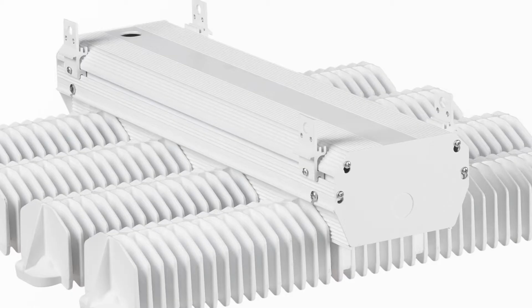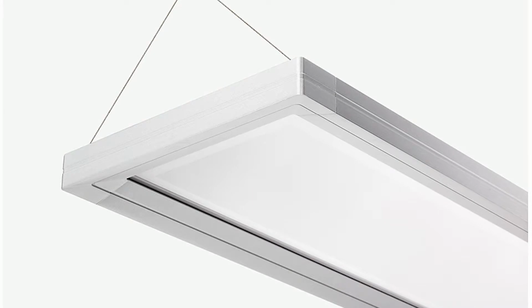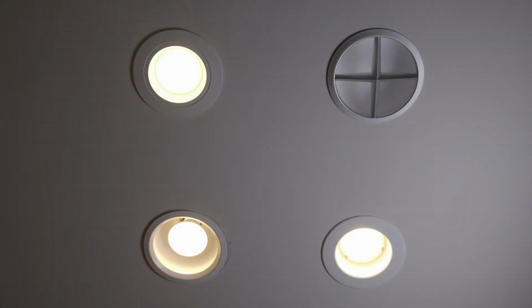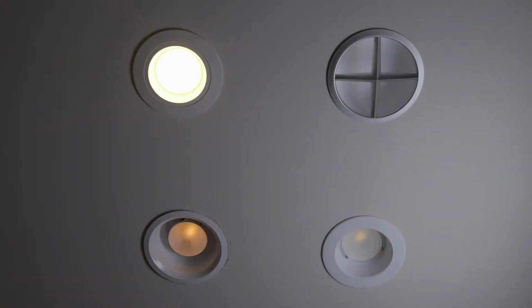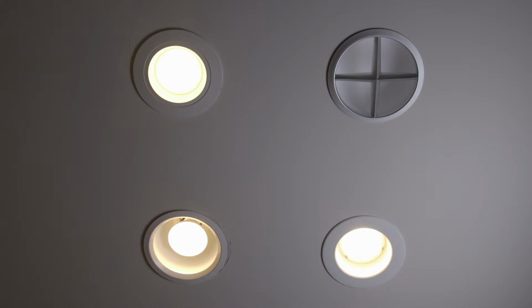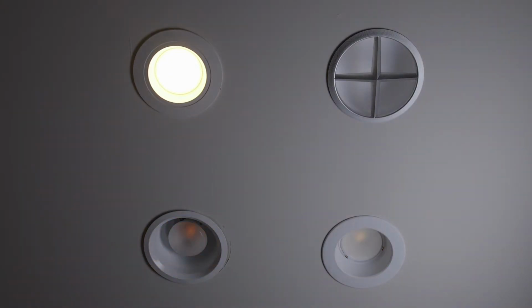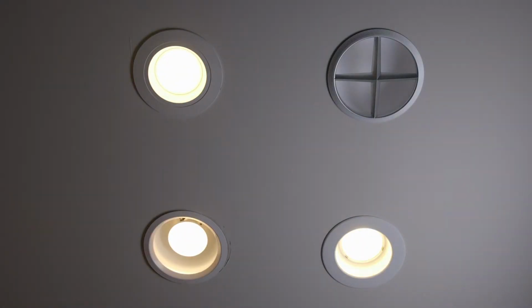So how many control steps are required? The answer depends on the type of lighting installed. Some types of lighting are great for dimming, while others are not. Sources like LEDs and linear fluorescent work well in dimming applications. As such, the standards require more control steps, or even continuous dimming, when using these types of lighting. Other sources, such as HID lighting, are more difficult to dim and usually cannot be dimmed to low levels. The Energy Standards require fewer control steps for those types of lighting.